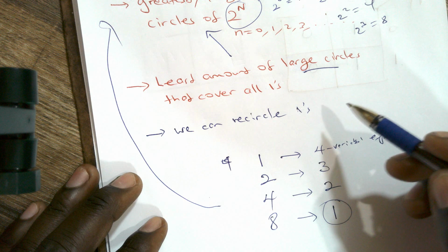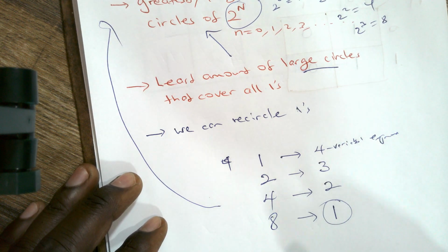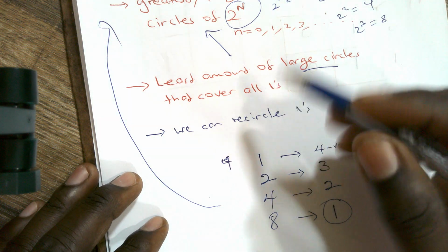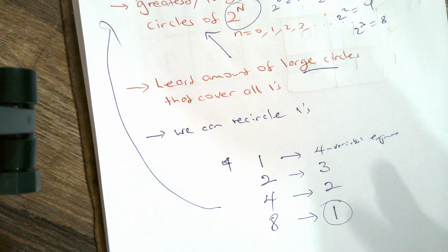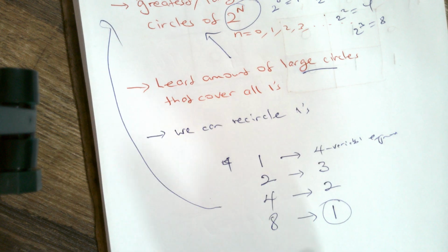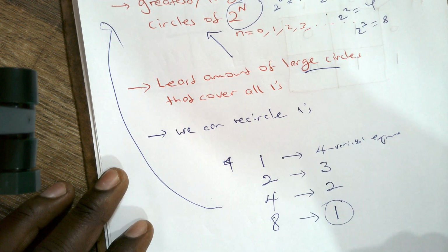The least amount of large circles minimizes the number of terms we will have. So together, these 2 rules will guarantee that we have the smallest expression. And that expression, once we follow all the rules, is going to be the minimum sum of product expression.